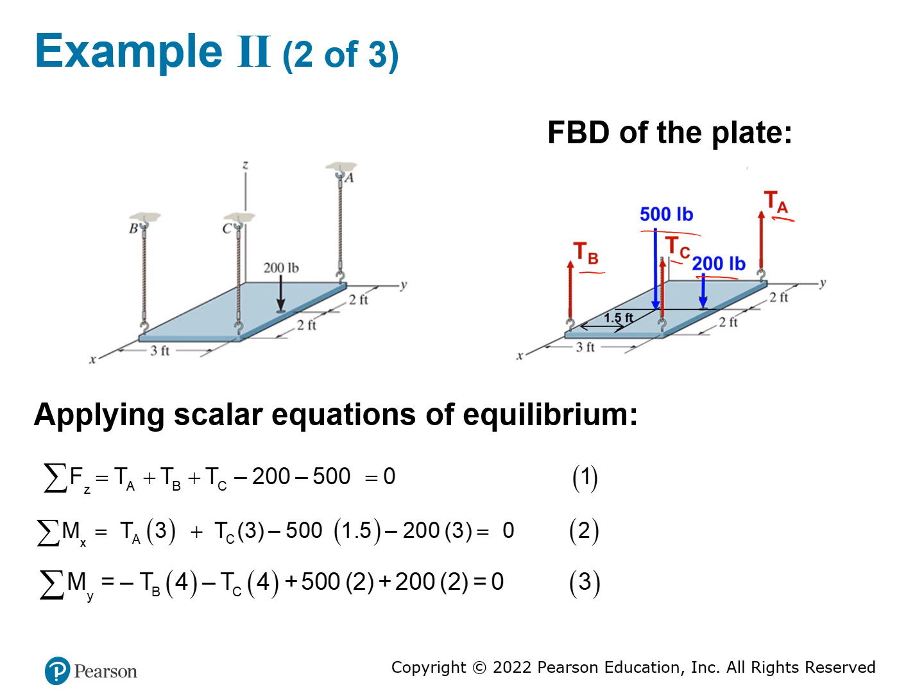Then you apply the equations of motion. Now, there's no X force and no Y force, so don't even use those 2 equations. The only option that you have is the Z direction, sum of Fz equal to 0, and the other equations have to come from the moment equation.